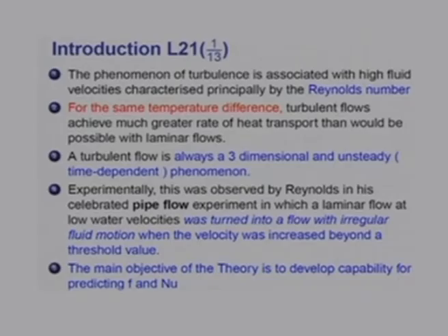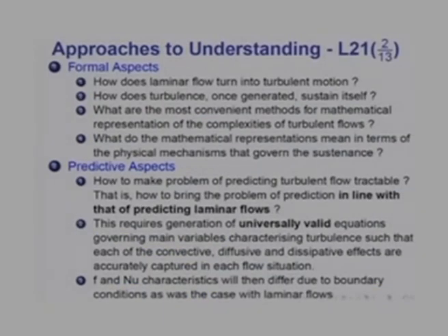Now, if you look at turbulent literature, there is a great deal of literature which I will call formal aspects of turbulence, which does not deal with prediction of friction factor and Nusselt number at all. Instead, it asks some very fundamental questions. Questions like, how does laminar flow turn into turbulent motion? That would be of great interest. How does turbulence, once generated, sustain itself? And now, this is a most relevant question as far as practical turbulent flows are concerned.